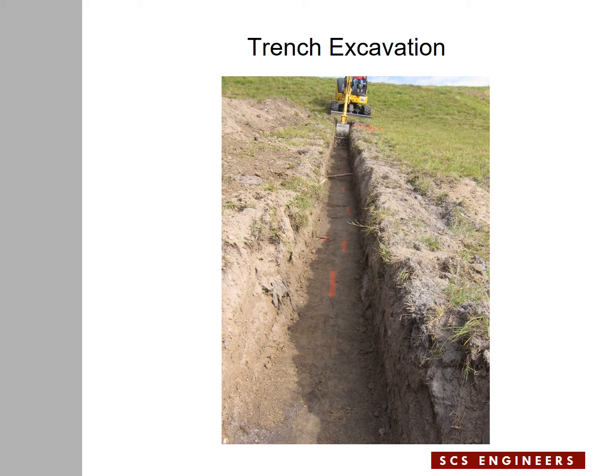If the composite becomes saturated and water comes out of the composite, it will get into the perforated pipe and flow very rapidly to the bottom. That would prevent saturation of the soil above the composite.